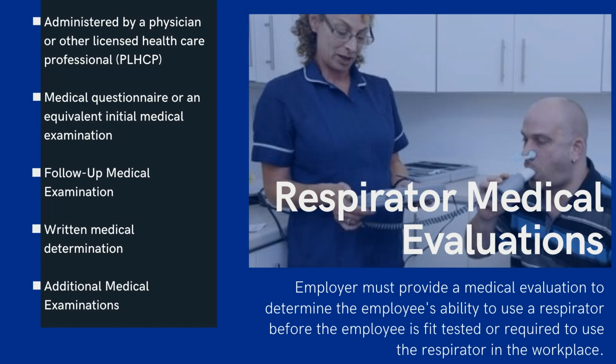Some respirator cartridges have an end-of-service life indicator to help a user determine when to change. In the absence of an end-of-service life indicator, a change schedule for canisters and cartridges must be developed based on objective information or data. You must describe in the respiratory program the information and data relied on and the basis for the canister and cartridge change schedule and the basis for reliance on the data.